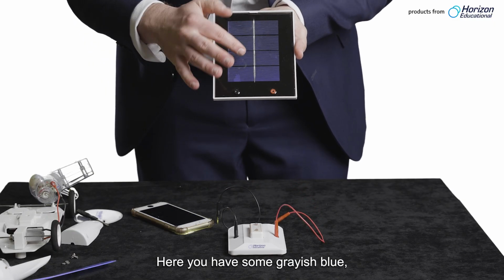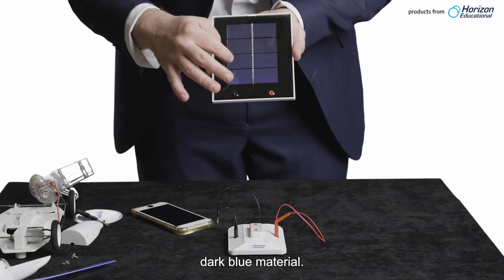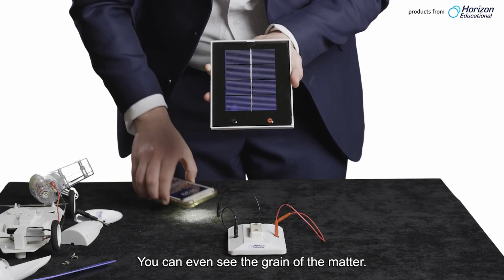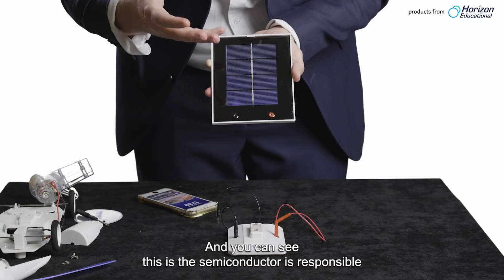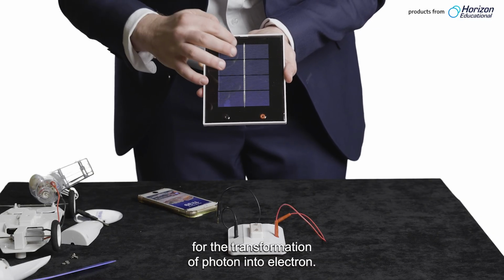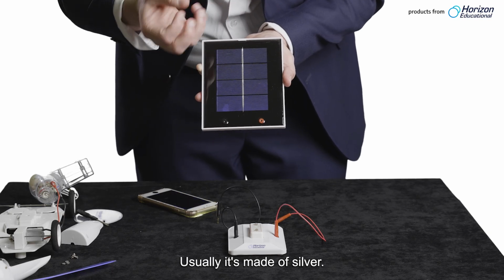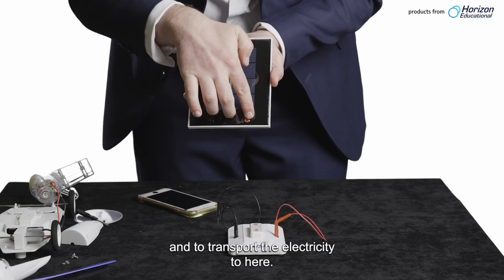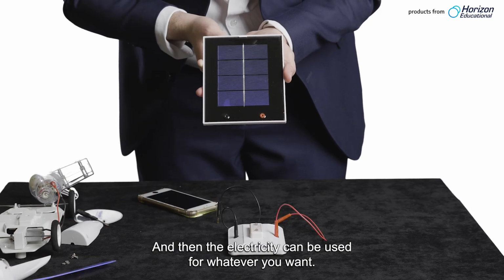Let's look a little bit further into this solar cell. Here you have some grayish blue, dark blue material. This is the silicon. You can even see the grain of the matter. This semiconductor is responsible for the transformation of photons into electrons. And here you have some metallic cables. Usually they are made of silver. They are used to extract the electrons and to transport the electricity to here. And then the electricity can be used for whatever you want.